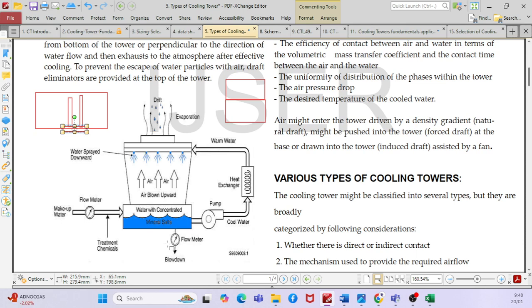When you calculate all these three losses, you can call them the water losses. Whenever you calculate the makeup water, you should calculate these losses and then give the makeup water from the potable water connection. But the potable water temperature would be different, right? No, it's okay. When you say 1000 GPM, the loss will be like 2 GPM.